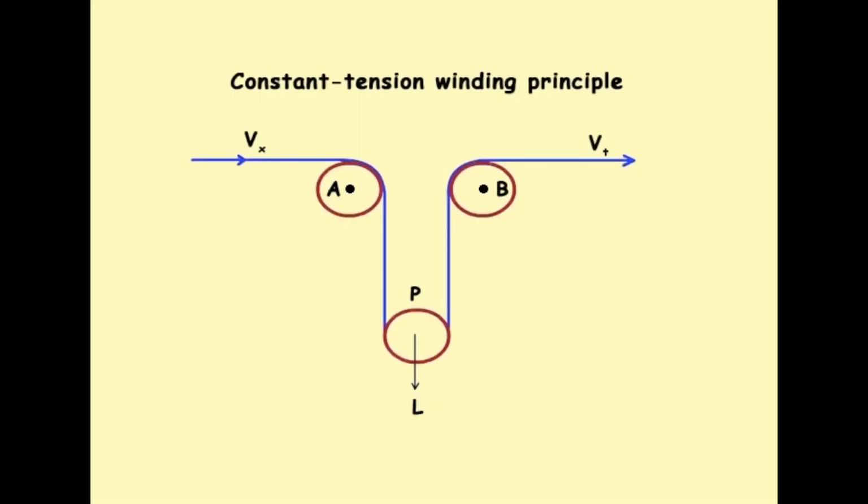In this, there are 2 small pulleys and one pulley which will be floating when the yarn is made to pass through. So, the weight of the pulley which is present in the center will provide tension on the yarn, and thus the breakage occurs wherever it is a little weaker.